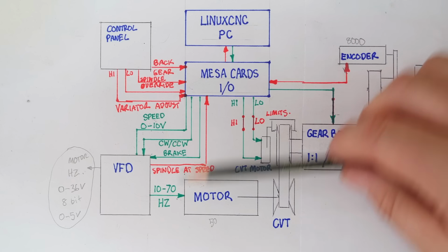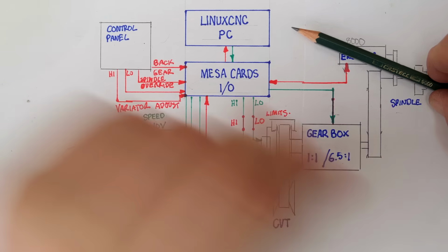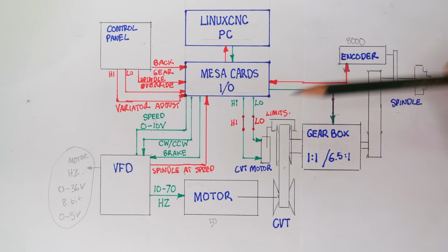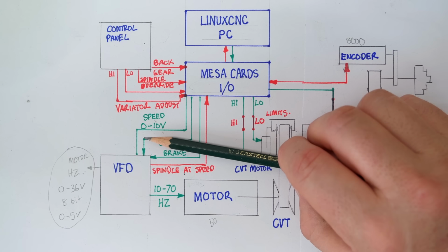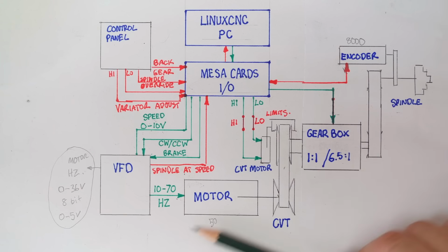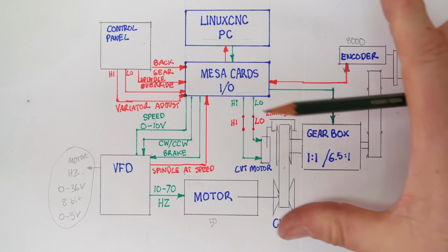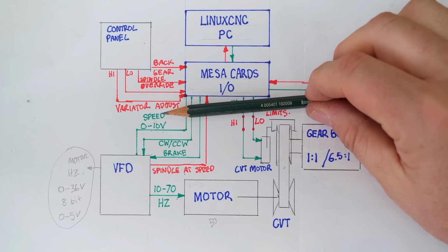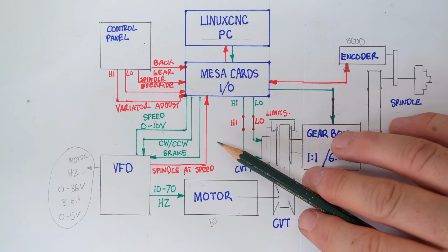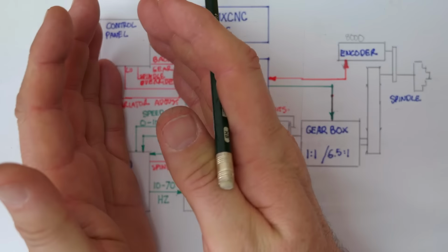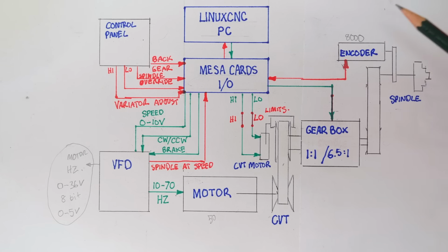And because the system was calculating that ratio 1,000 times a second, the first time it calculates it, it's seeing 0 speed out, maximum speed in, and sees a nearly infinite gear ratio. As the system accelerates, that gear ratio will reduce, and eventually at a steady state, you'll be able to read a reasonable number. So what I was trying to do with software was put a gate on that calculation: do not calculate gear ratio unless you're at steady state.